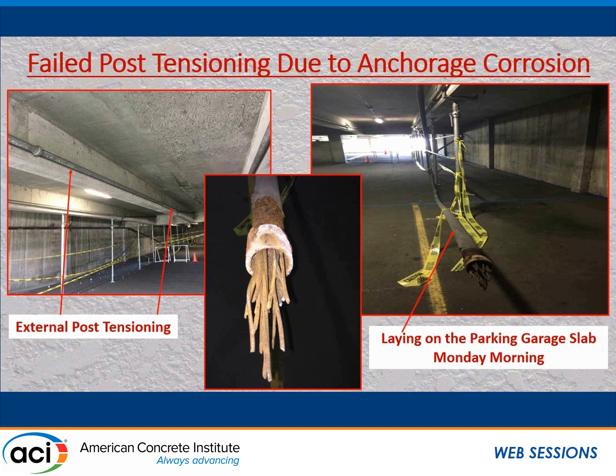So there are a couple of things that probably happened. This failure occurred essentially 40 years after it was probably installed; they don't know the exact time. And what I will say is the condition of this grouting of the duct has led ACI 546 to have a subcommittee to look at the use of prepackaged materials, and part of what stimulated it was the poor grouting of post-tensioning ducts. So we have to do a good job of protecting it.